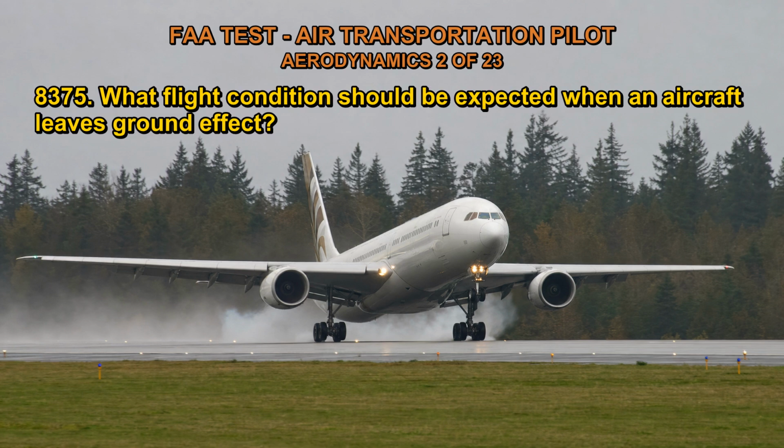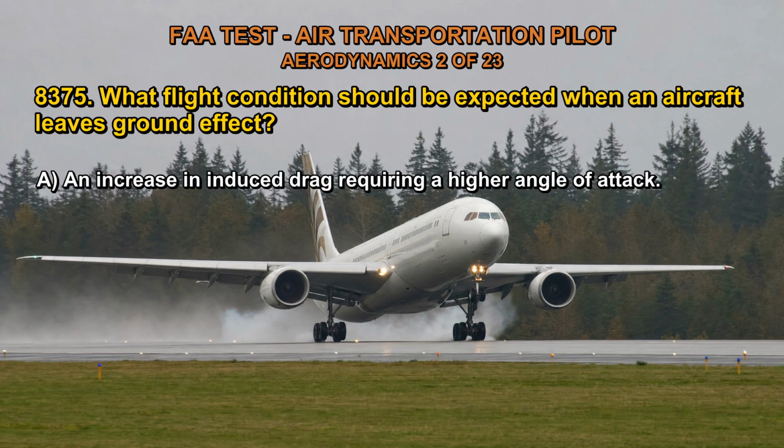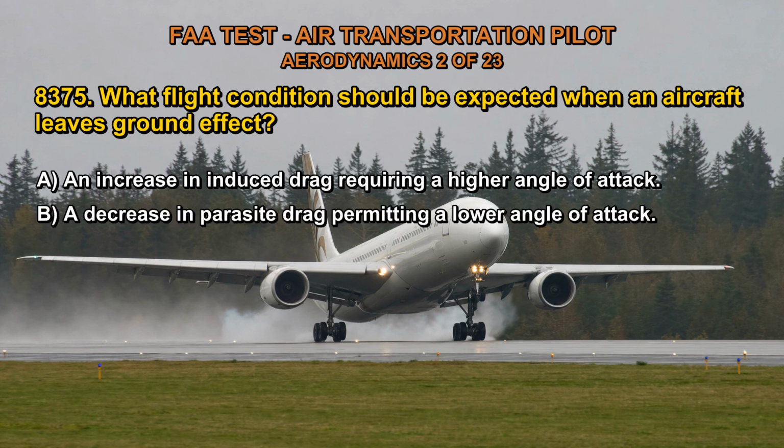8375. What flight condition should be expected when an aircraft leaves ground effect? A. An increase in induced drag requiring a higher angle of attack. B. A decrease in parasite drag permitting a lower angle of attack. C. An increase in dynamic stability.